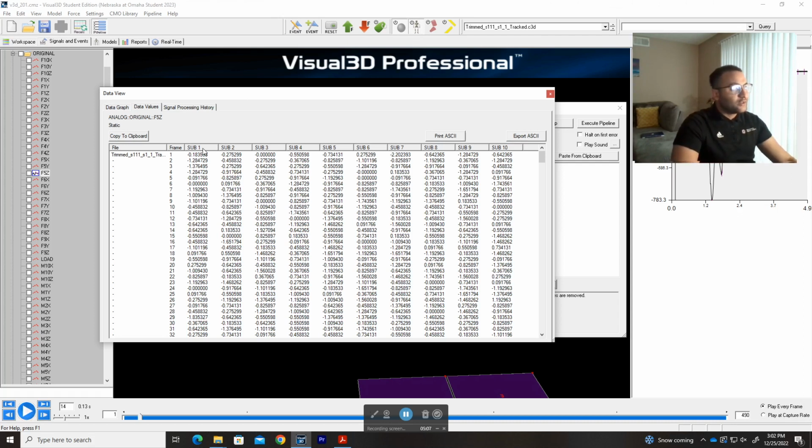So that's why the first column here is always the motion capture frame rate for the kinematic data, and then all the additional columns in here are the additional data that are used as a multiplication. I collected 1,000 frames per second for the kinetic data, and here it's just basically a multiplication. So you can only choose 10 times 100, to get 1,000 frames per second. If you want to collect at 800, then you just choose 8 times your motion capture.